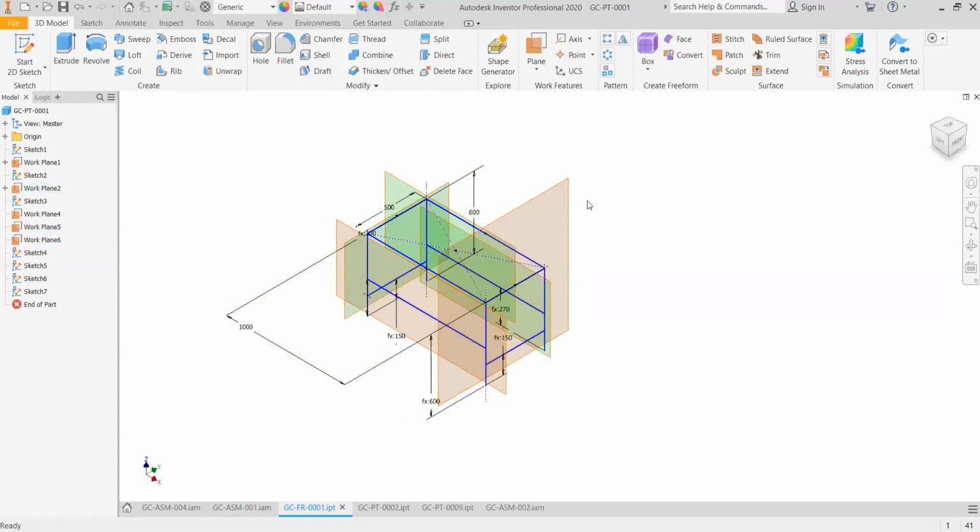And I didn't have to put any rule right in here. So I just want you to know that you don't have to start with the rules. But now the most important thing at this level, when you're designing a part, is to always declare your parameters properly. That's the most important thing. So that's the first thing I said we will learn here, declaring your parameters.